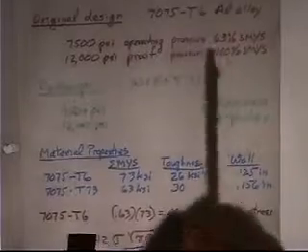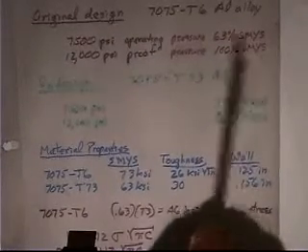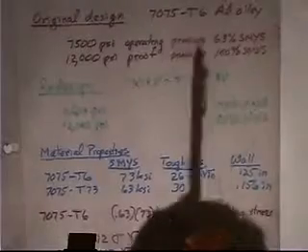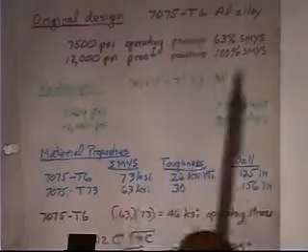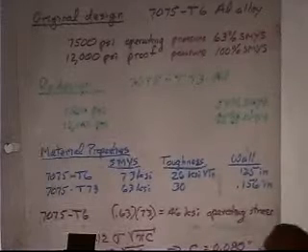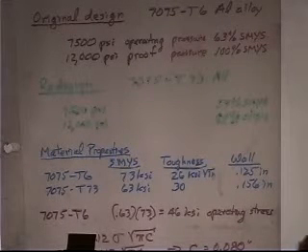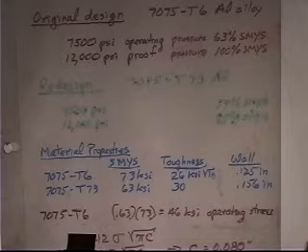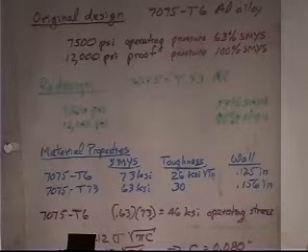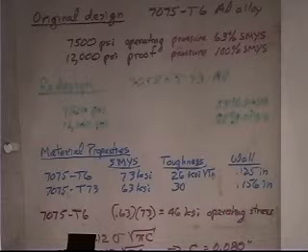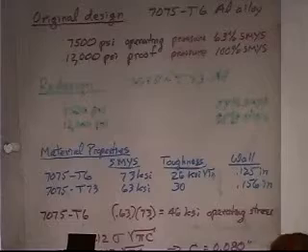That happens to be 100% of the specified minimum yield strength. When they went to 12,000, that's how they selected it. They're going to operate at roughly 2/3 of that, and that seems all right. Well, it turns out that it cracked, and in fact, it cracked in a brittle fracture such that they couldn't get the sail up, and they had to have a spare on board. Why are you trying to keep the weights down, you know? Although I guess maybe they take the spares off when you're really in competition. This was probably just in training.